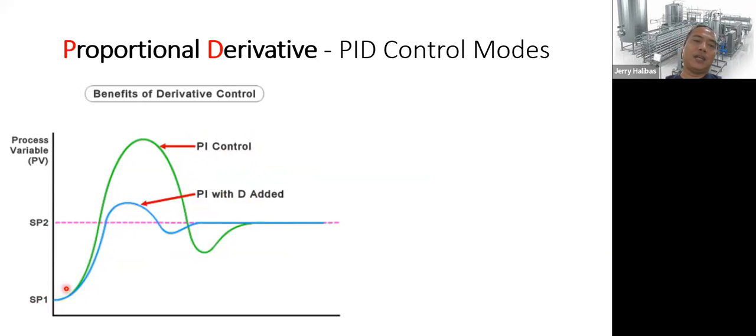It can anticipate the excessively high output overshoot. So it is nice when you add derivative. It can anticipate the future output. The term is anticipate, not really predict, but the correct term is anticipate. It has no artificial intelligence, or even intelligence, to predict, but rather its characteristic is to anticipate because of the differential or derivative action.